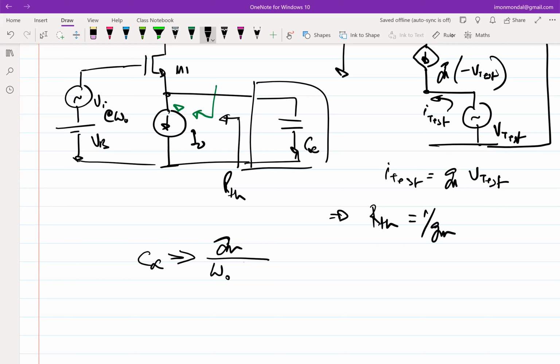So if, let's say, you have a band of frequencies for which you have to satisfy your criteria, right? Let's say the frequency band for which the common source amplifier is supposed to work is from 10 megahertz to 100 megahertz. So for which number, 10 or 100, are you going to fix the C infinity? 10. Why 10? At 10 megahertz, right. Exactly, if it's a short at 10 megahertz, then definitely it's a short at 100 also, right? So we start off with the worst case condition. Okay, fine.